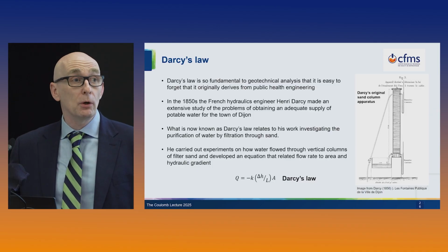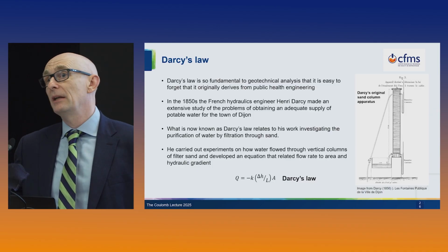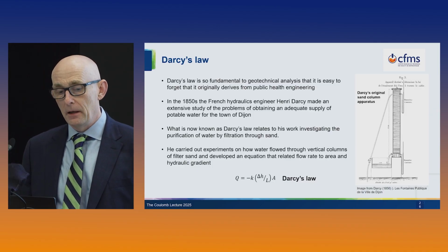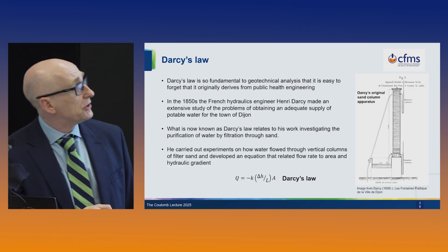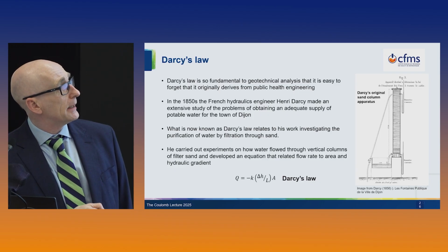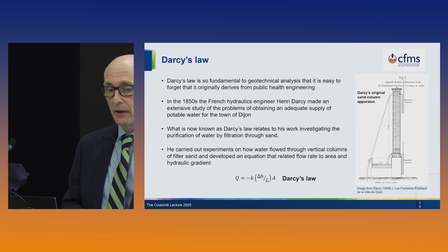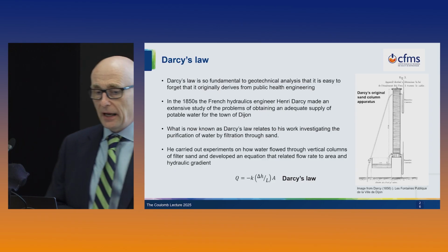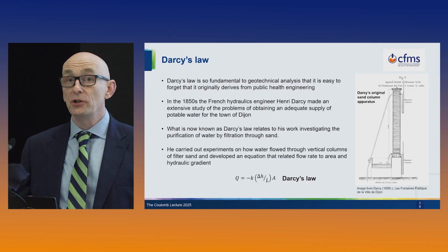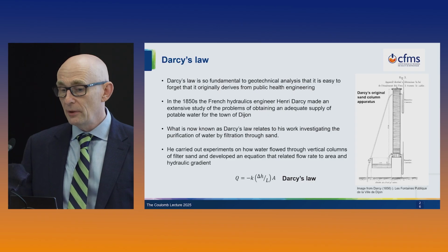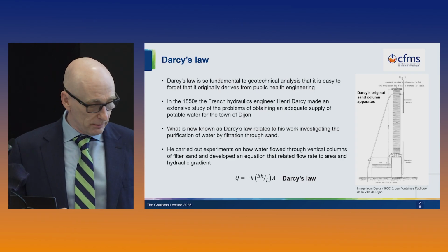sand columns. And if you go to water treatment works nowadays, there are beds of sand through which water is percolated. So Darcy had this sort of experiment. It's one of his original plates, where he has a sand column through which he passed water and made various observations. And he developed the equation that we know as Darcy's law, that related flow rate to area and to hydraulic gradient.